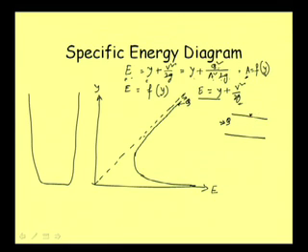Suppose I change the slope, then our depth will come down, and when depth comes down, your E from this part will be less. But when depth comes down and Q remains the same, our velocity increases, so this component will increase. So with the change of depth, E is coming down sometimes and then it is again increasing, and then we get a minimum value.